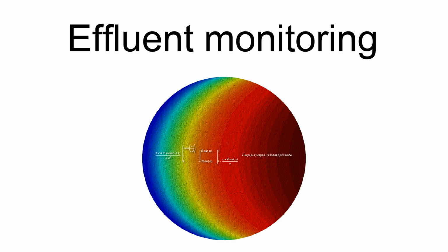CPAMs are used to monitor the air effluents from nuclear facilities, notably power reactors. Here the objective is to assess the amount of certain radionuclides released from the facility. Real-time measurement of the very low concentrations released by these facilities is difficult. A more reliable measurement of the total radioactivity released over some time interval, days, perhaps weeks, may in some cases be an acceptable approach.